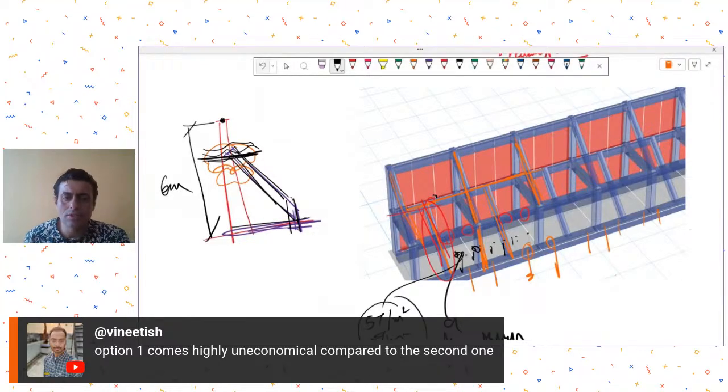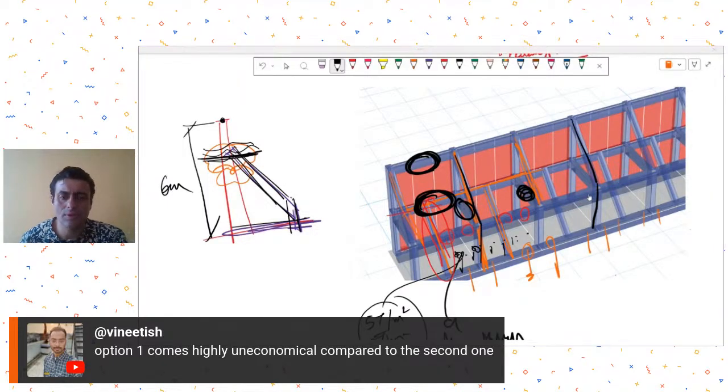This beam can be eliminated, it's not helping you. Just have this tie beam and this column, and that's it. This horizontal member is also not helping you. So just have two elements and try to redesign. Just have this, that's it. I think most of the elements that I see are not required. There are just too many elements that you have provided, and have toe and heel slab with it. Clear? So try this out. It might be helpful for you.